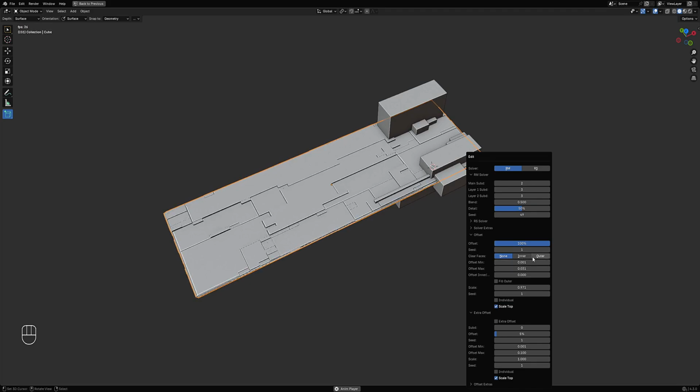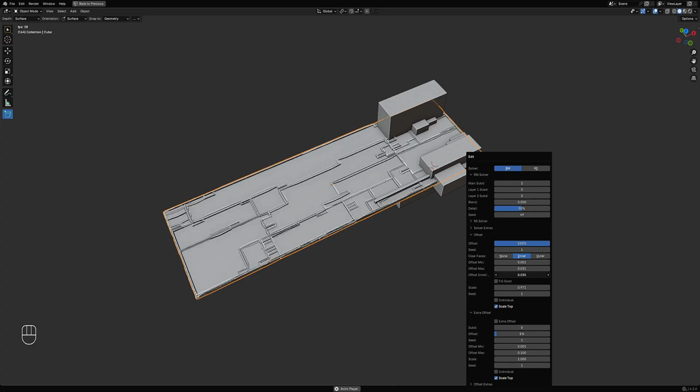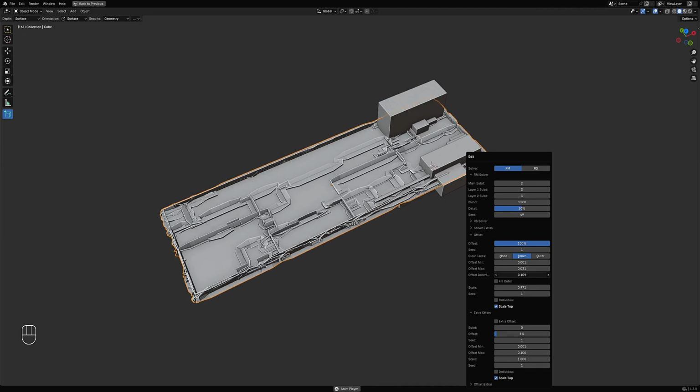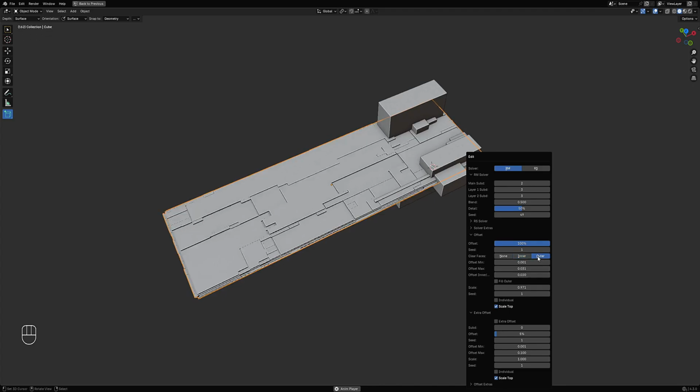So with inner and outer, you can use the offset inner outer parameter. It doesn't work with none, and it only works with inner and outer. So for example, with inner, you can increase the thickness. So right now there's a problem with having a straight distribution of the thickness. You can see that the corners are kind of, everything is kind of being twisted while you increase the scale or the thickness of the inner offset. With outer, there's no problem. So we're going to use outer instead.